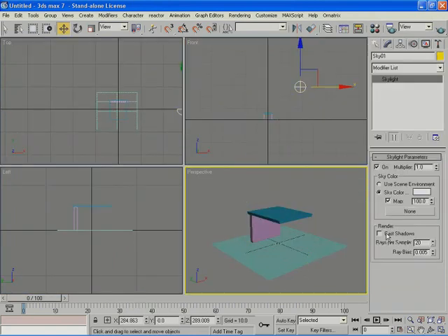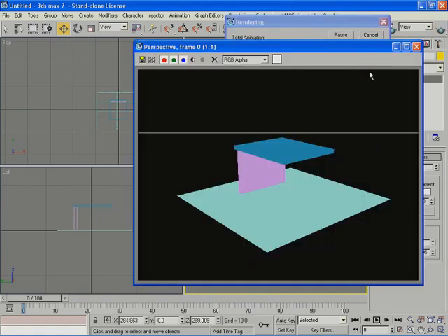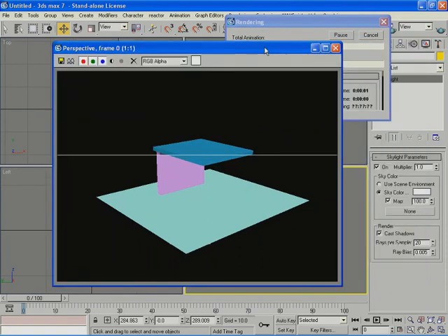Now this would take a bit of time to render, depending on the samples that I choose. But here I would see that even though I have a skylight, I have automatic darkening underneath that box here. This is similar to the ambient occlusion that we saw the other time. So now, if I had to simulate a daylight system, I would add a skylight, and on top of that, I would add my spotlight to have the sunlight shining through.